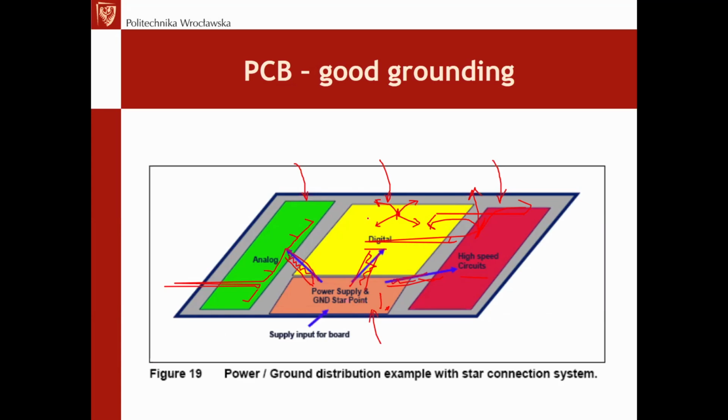So if we place, for example, high precision analog components close to high frequency circuits, then the EMI noise from the high frequency circuits will be delivered through the air, through electromagnetic waves, to the analog components, and good grounding technique would not prevent this because it goes wirelessly. That's a problem. That's also the second advantage of the sorting: when we physically separate the noisy components from the sensitive components, we avoid this kind of trouble.